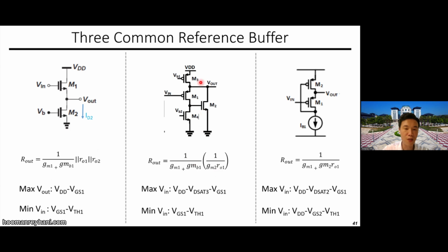Well, you can even do that with the same branches by cascoding. You feed the internal loop over here back to the cascode device, so that you can have a similar kind of gain boosting of the impedance over here. So this will be equal to 1 over gm1 plus gm2 times ro1. I would say these two architectures are more promising.